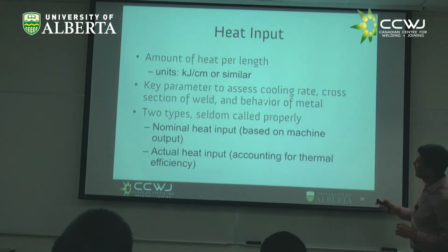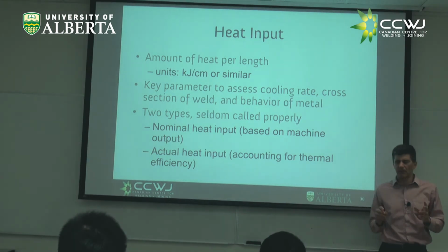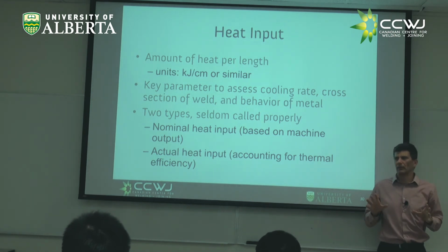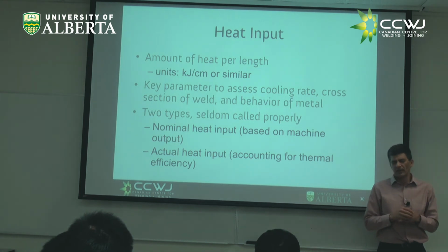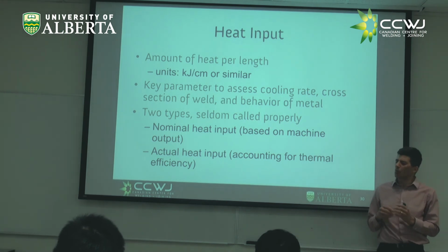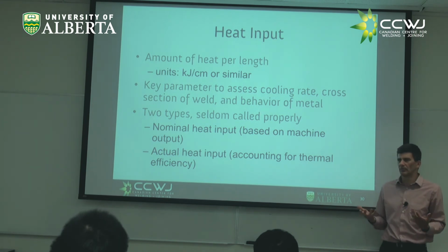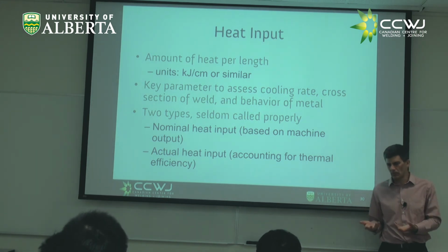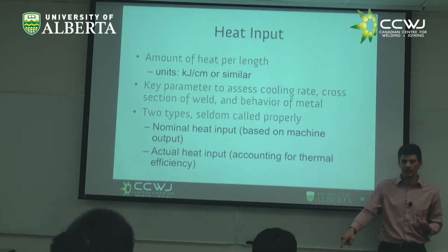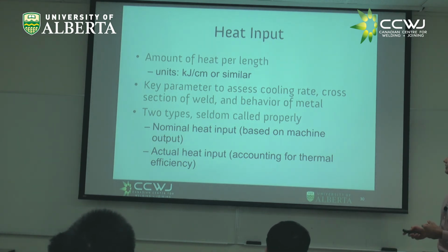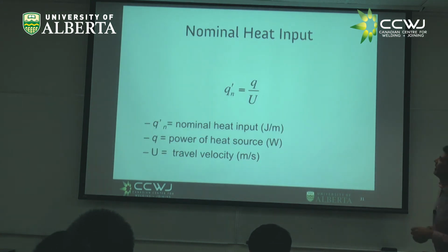So heat input, this is very important. People seldom speak clearly, but there are two heat inputs. One is the nominal heat input, is how much do you think you're putting into your material? That's the nominal. And then they say actual heat input is how much actually went into the material. Of course, they are related by an efficiency, and the efficiency is never 100%. If you're near a weld and you feel the heat, that heat you felt is a heat that this plate didn't feel, right? And actually, that's quite a bit. And we're going to have a unit just on these efficiencies.